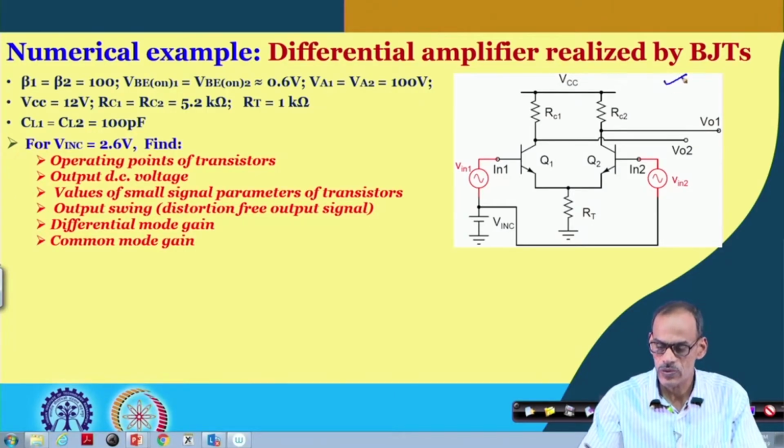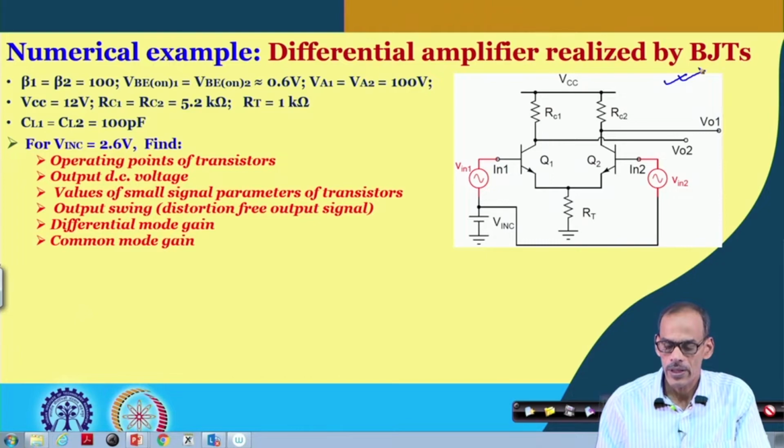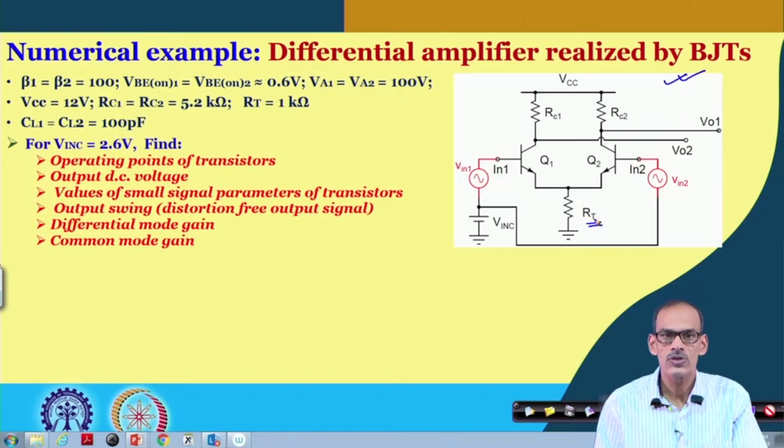This is the circuit we have discussed before, and you may recall that in most of our analysis we split the resistor RT into two identical elements in parallel. The intention was to get more insight into the circuit, particularly to see how the differential signal and common mode signal propagate from the primary input port to the primary output port.